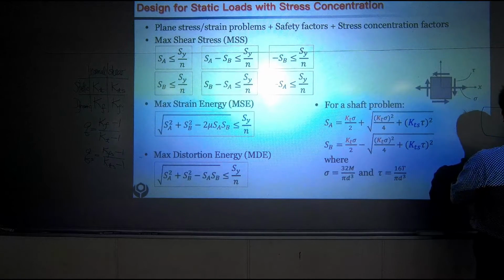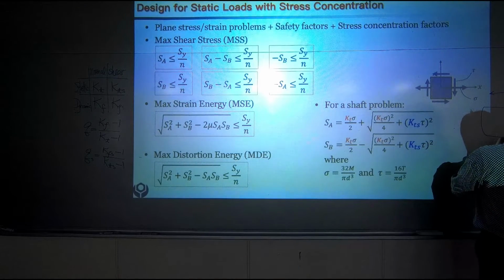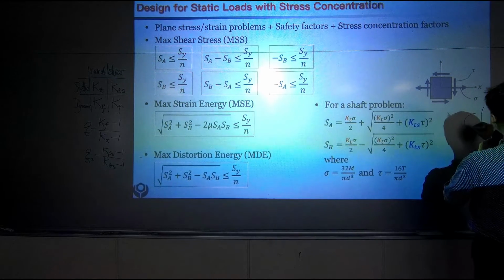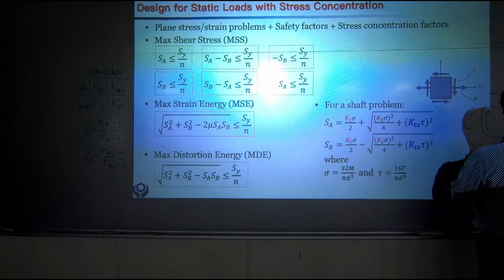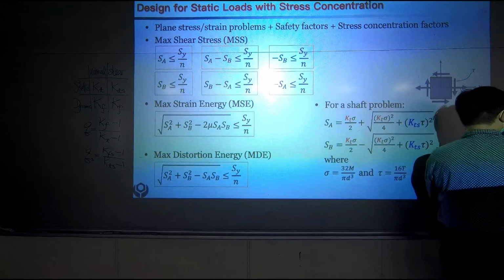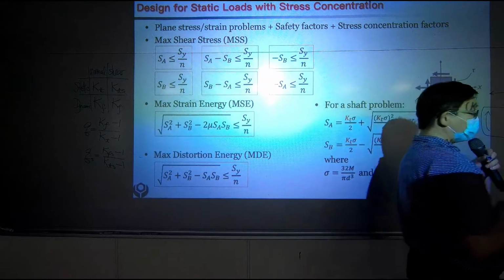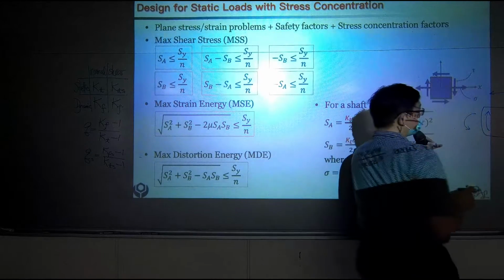If we happen to have bending and twisting at the same time, so moment and torque, then those corners are carrying both tensile stress and shearing stress.